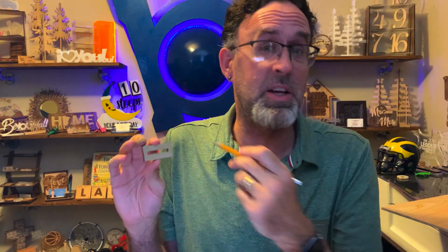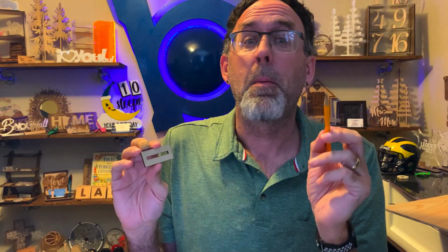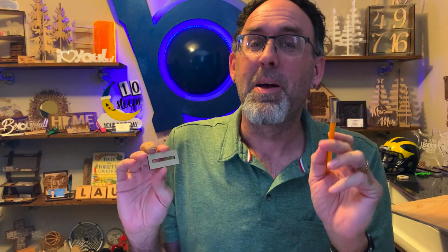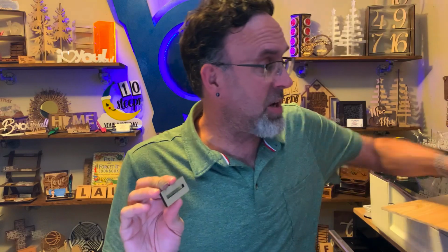Because, remember my last video earlier this week on kerf? What's going to happen is your 0.208 is going to end up fitting something like 0.218, because of the kerf of the laser. So I would probably make two of these. Make one that's 0.208 and one that's, you ready? There's a lot of numbers. 0.01 smaller.